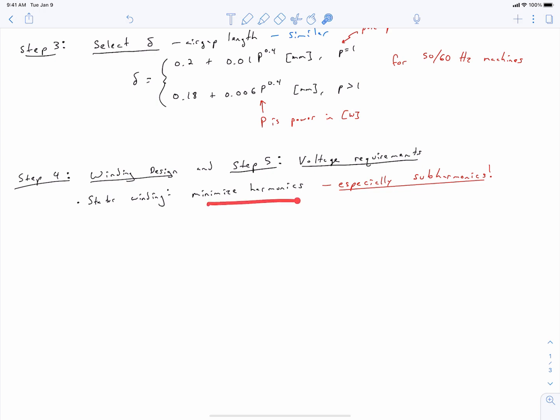The reason that this is so critical is that in the induction motor, your air gap length is typically small, and short air gap lengths mean that your rotor is exposed to more space harmonics from your stator winding, so that will cause losses on the surface of the rotor. In addition to that, the surface of your induction motor has this cage rotor on it.